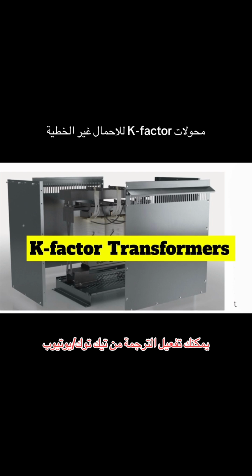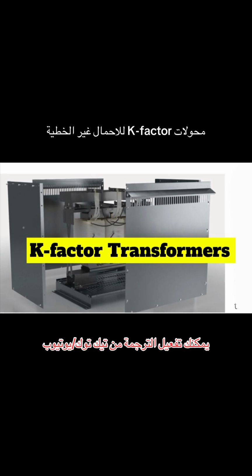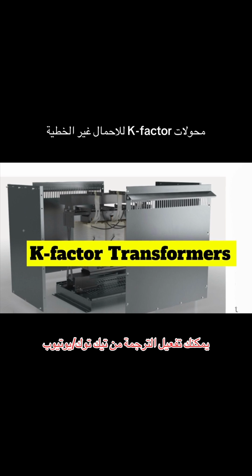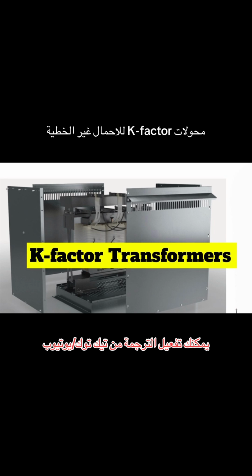The paper also briefly mentions these things called harmonic mitigating transformers, or HMTs, and says they are different from K-factor transformers. What's the deal with those? So HMTs are a step up in terms of technology. Unlike K-factor transformers, which are designed to withstand the heat from harmonics, HMTs are actually designed to reduce the amount of harmonic current flowing in the system. They use more complex designs, often with multiple sets of windings and special core configurations that can cancel out certain harmonic frequencies. So they actively fight the harmonics instead of just enduring them.